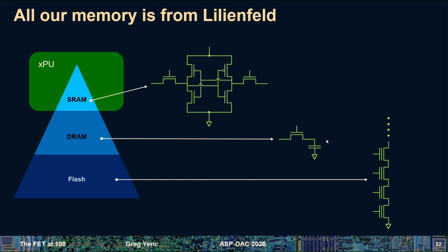You also have DRAM, which is simple from a circuit standpoint. You have one pass gate opening up access to a capacitor. So you just drive your voltage, which is going to fill up your capacitor with electrons, close it off, and it'll sit there. It'll leak. The capacitor will leak in modern nanometer circuitry because you make the gate oxide small and what have you. So it forgets what it's doing, and then you have to refresh it. I think I'm going to talk about that, or may have already. We'll see how it goes. I think I might not get there by the time you hear this. Let's talk about DRAM a little bit.